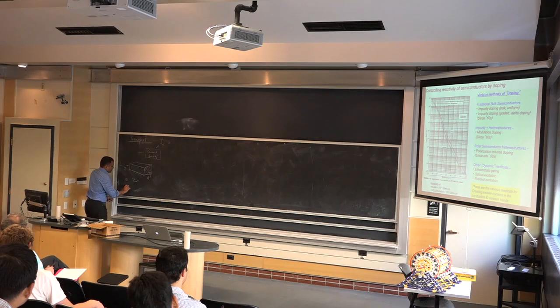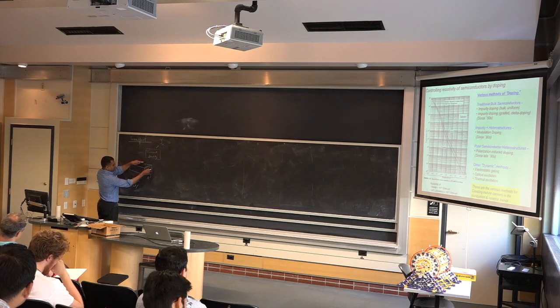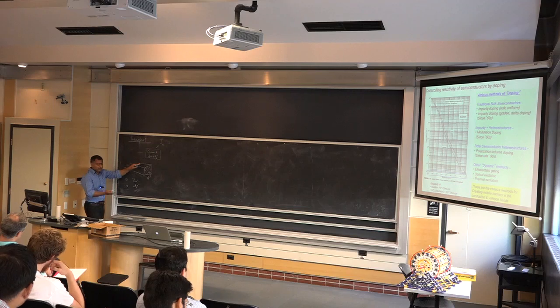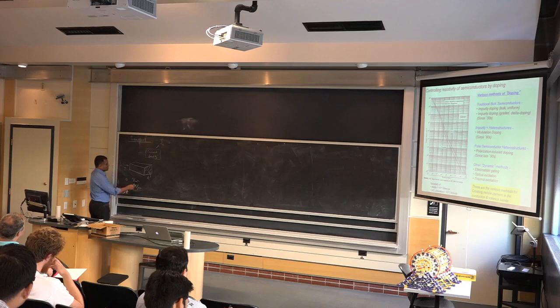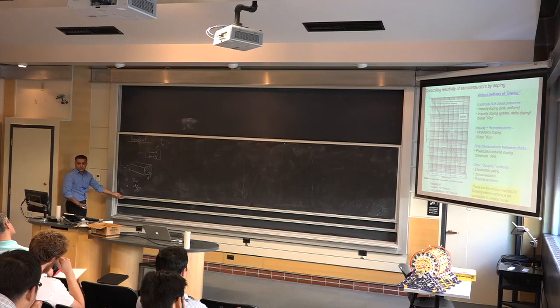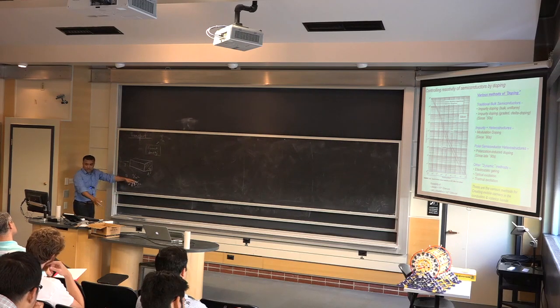In 2D, typically what is used is milliamps per micron. If you have 2 dimensions, you have just a line. You don't have any area to flow through, you just have a width. So you have current per unit width. You can think of amps per meter, or this is typically what's used in transistors, milliamp per micron, because today transistor widths are about a micron or so.